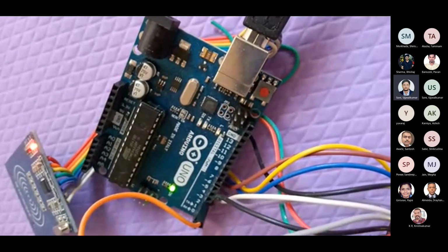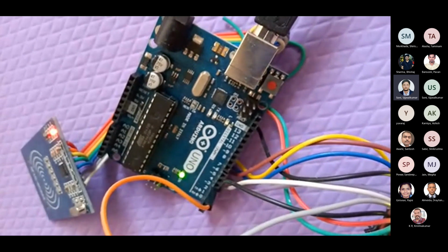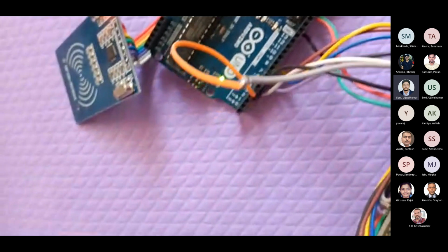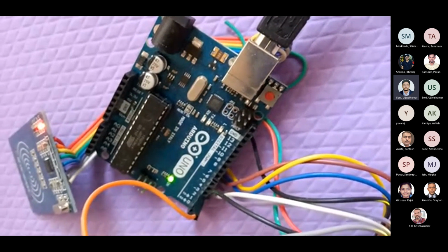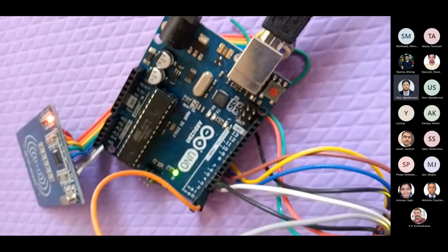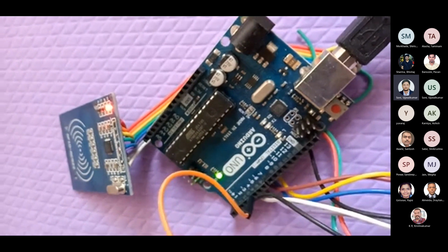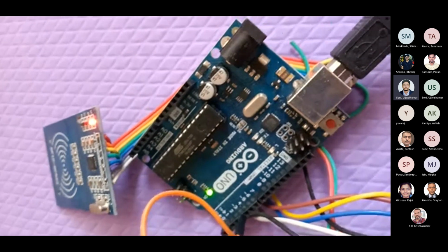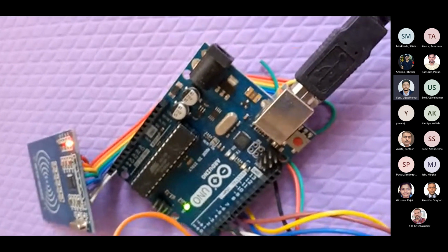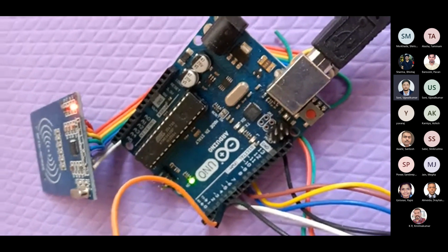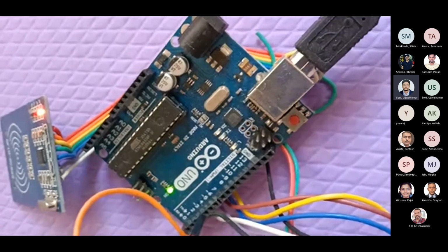It's very easy to find out the exact problem with this IoT device. And if there is any issue with any of the modules, you don't need to replace the whole microcontroller along with the other modules. If you are having a problem with the RFID module, you can easily remove it from the jumper cables from here and replace it. And again, using AWS Greengrass, you can also update the firmware onto this ATmega328 chip. It's going to be OTA.